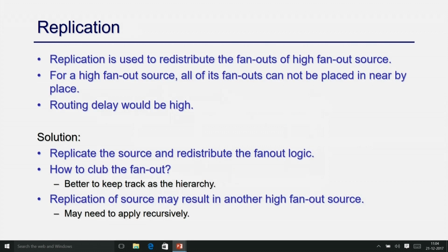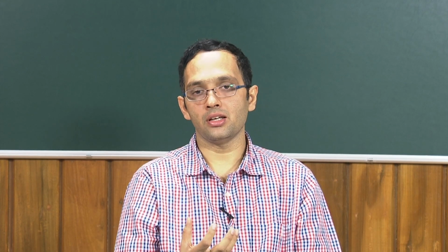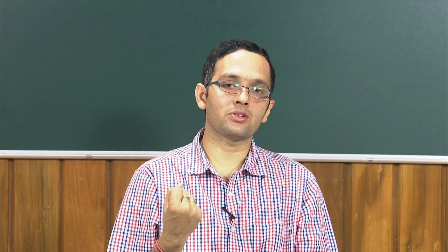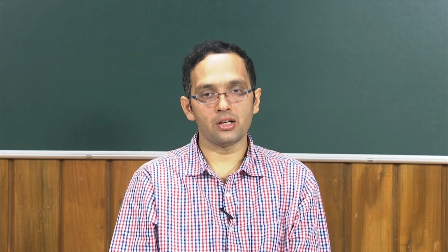The last one I am going to talk about is replication. What is replication? All the previous techniques I talked about are just to reduce the logic delay, that is the computational logic delay. The other factor that I talked about was the routing delay, right. So, replication is a strategy that actually helps to improve this routing delay.